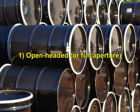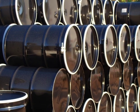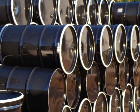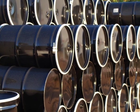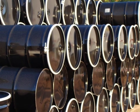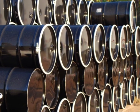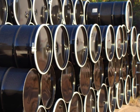Types. Number 1. Open-headed or full aperture. Used for dry products, semi-solids, and viscous liquids. Closures for open-headed pails and drums are full diameter lids. The seal is usually effected by a rubber or plastic gasket contained in a channel in the lid.